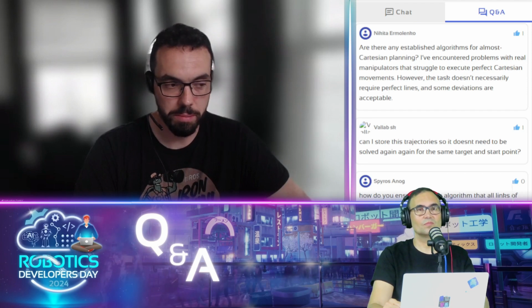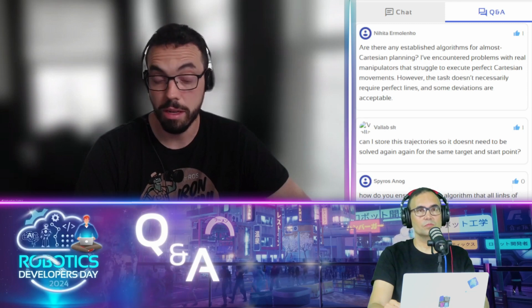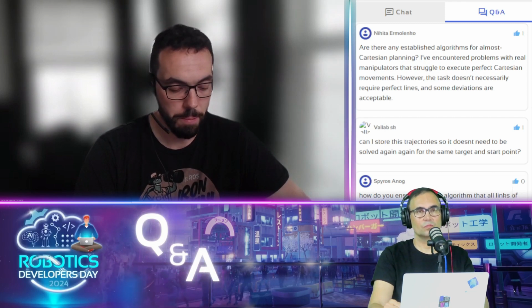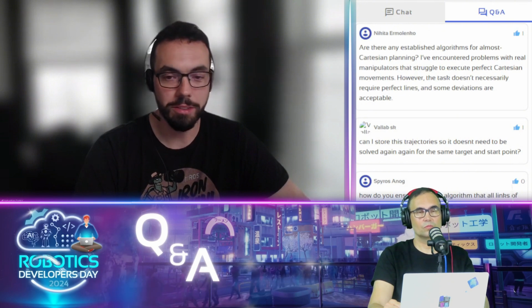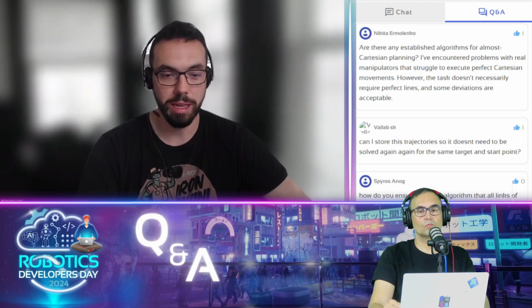You can also, and this is really where the world is going nowadays, use trajectory optimization. Instead of having hard constraints on a trajectory to meet them exactly, you can create soft constraints, or not even have constraints, and only formulate this as a minimization problem. Give me any valid trajectory that minimizes my distance to the desired Cartesian path.